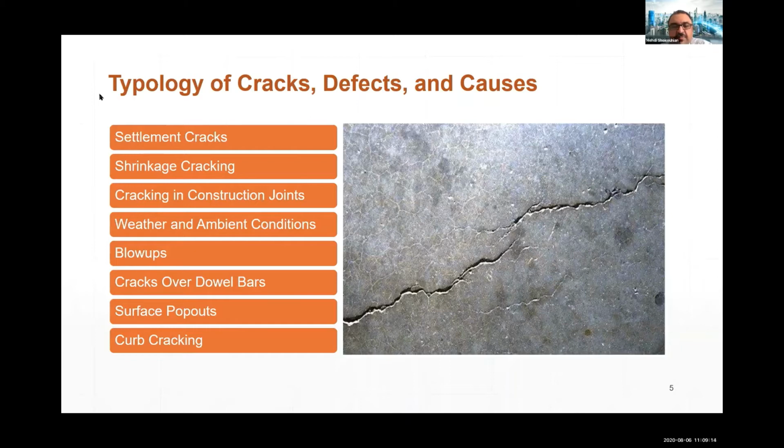When it comes to the repair of distressed concrete pavements, few options are available. It's very difficult and time-consuming to repair hardened concrete. Full depth and partial depth repair, slab replacement, crack sealing, crack stitching, and staple pinning are some of the techniques that can be used to repair distressed concrete pavement.